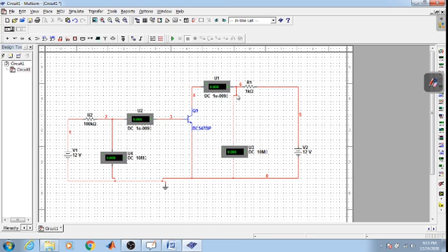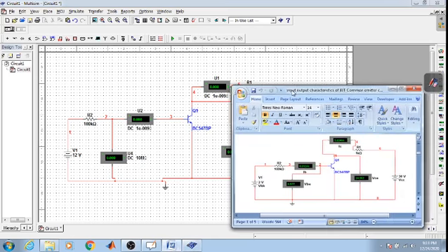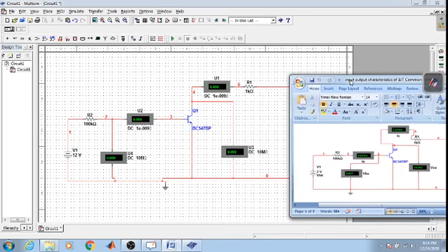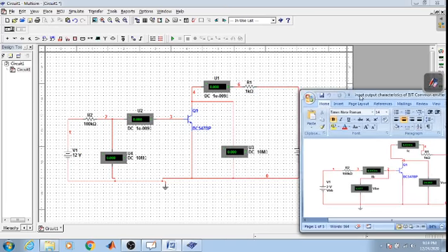If you want to connect this to here itself, you just select the line, then shift delete, it deletes that line, it's a wire, you click here and then you can click here. So that completes the circuit. So this is your circuit, and the circuit is ready to study the first experiment.